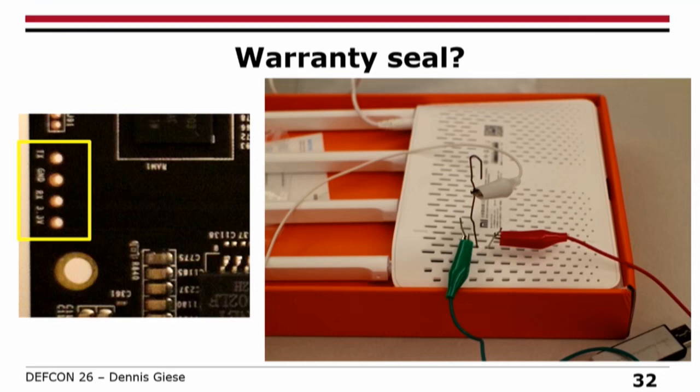This is especially important for this device because after the first power up, they close down the serial port. But if you connect to the serial port before you power it on for the first time, you can reset this flag which disables the serial port, and then you have the serial port forever. So very important for this device.